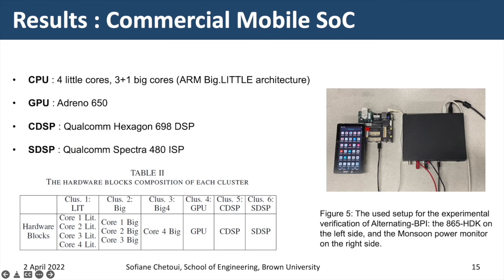To validate our results further, we use a commercial mobile SoC. The setup shown in figure 5 is used, where we use the 865 hardware development kit and the Monsoon power monitor to measure the total power consumption of the board.